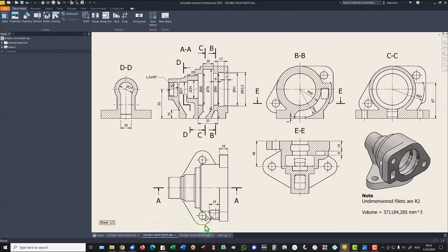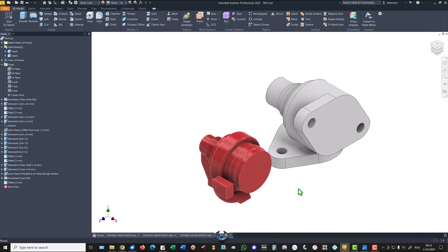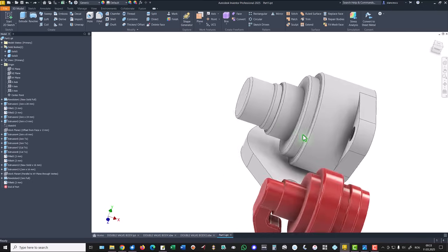We continue with this feature. Dimensions are here. 19 is the thickness of this contour when we apply extrude, of course. Radius 60, distance of 67. We use this plane for that new sketch.